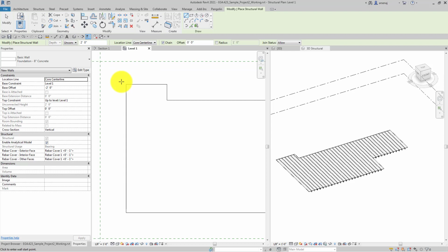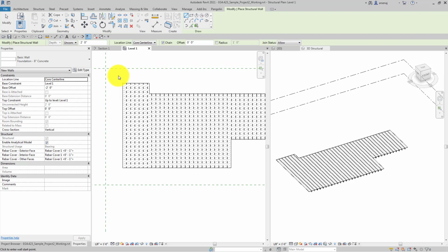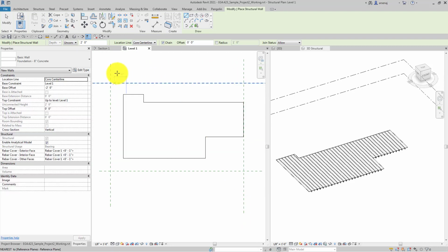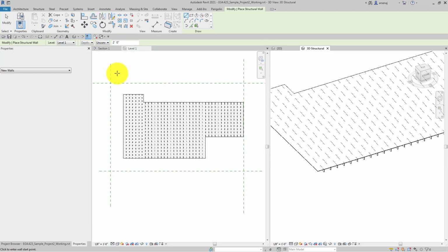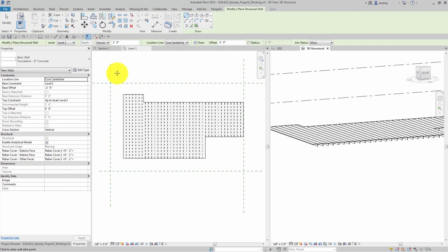In this instance it makes sense because if you're creating a structural wall, particularly for the foundation, you're going to set the top of the wall, and then you're going to want to go down, so that the wall is below the floor line, because we're creating a structural foundation wall. So it's automatically set to unconnected 2 feet. As you can see here, the base constraint will be -2 feet, and the top offset